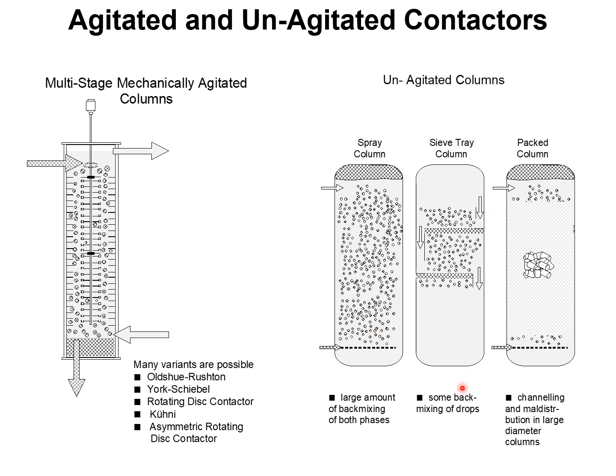We have a sieve tray column, very common in sulfolane extraction for, say, producing food-grade hexane. Several industrial units employ the sieve tray contactor. We have the packed columns for liquid-liquid contacting. The most common ones that I'm aware of are the RDCs in this category and the sieve tray columns in this category. I have a few remarks to make about the rotational speed used in the agitated columns. The choice of the rotational speed is important because the number of rotations per second dictates the drop sizes.